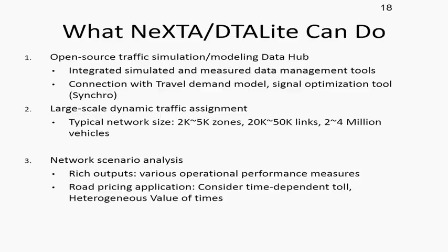So what can we do in the DTALite? We can do a lot of data importing and exporting. For example, we can import data from GIS packages such as shapefiles, and also we can import traffic flow and traffic demand models from static traffic planning packages such as VISUM, TransCAD, or Cube.